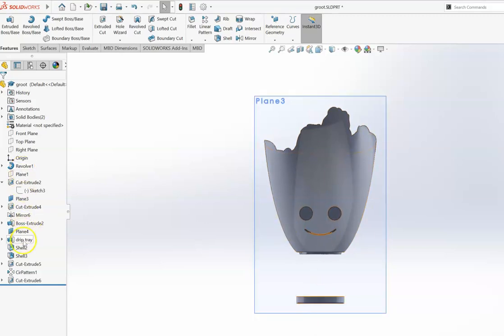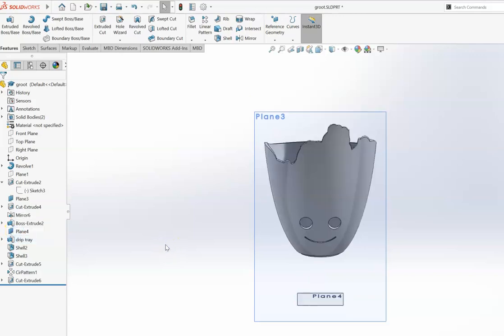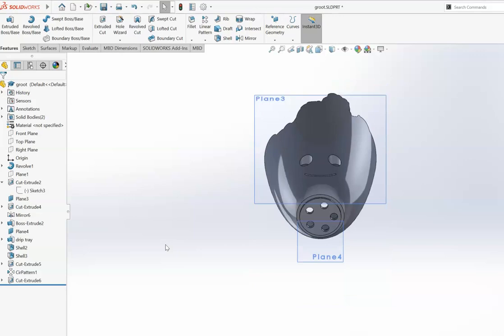So down here you can see that I have identified the drip tray and given it a name. You just have to find the drip tray. So as soon as you've clicked on the thing that highlights the whole drip tray, if you click on the little icon, then it comes up with a menu and you click on hide. And you'll see that the drip tray disappears.